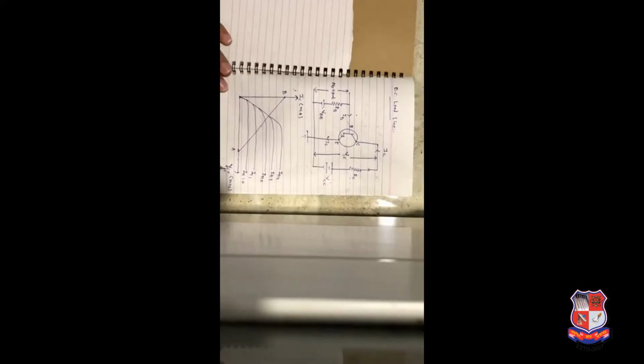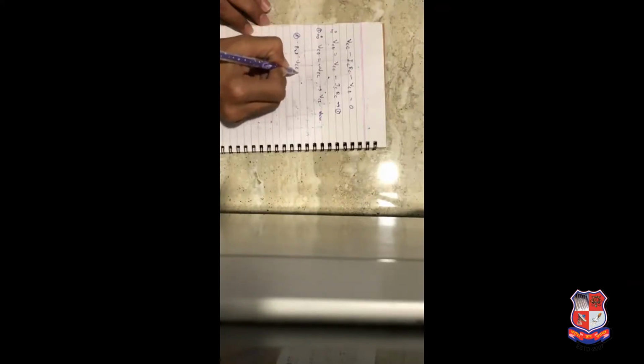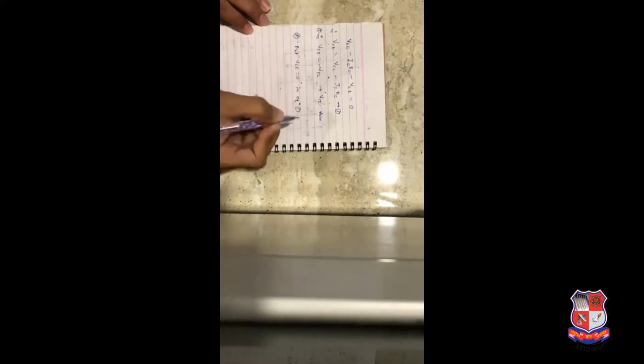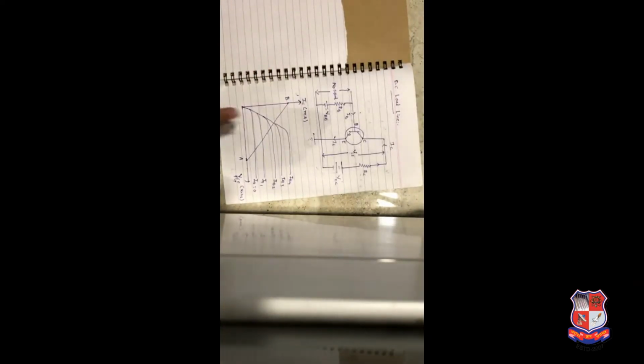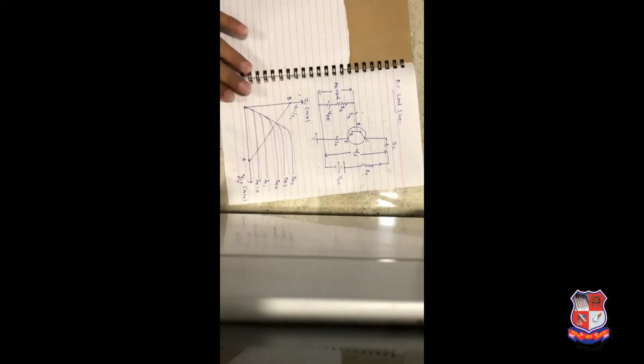Now point number 2: your collector current IC becomes maximum when your collector emitter voltage is 0. So put VCE equal to 0 in equation 1. Therefore 0 is equal to VCC minus ICRC. Therefore IC is equal to VCC by RC. So this one is the maximum. This gives the collector current axis as shown in the figure. This point is indicated as VCC by RC.